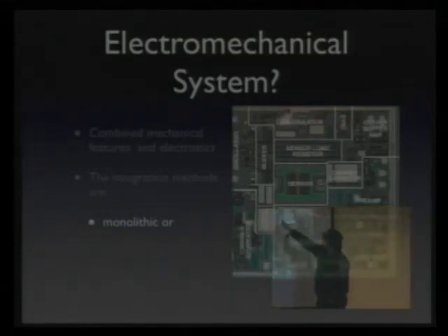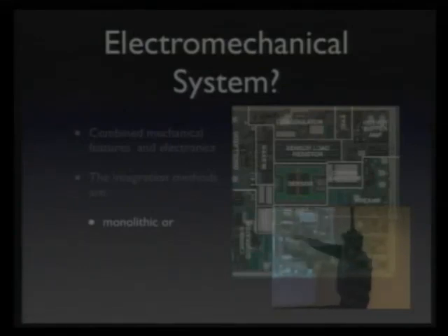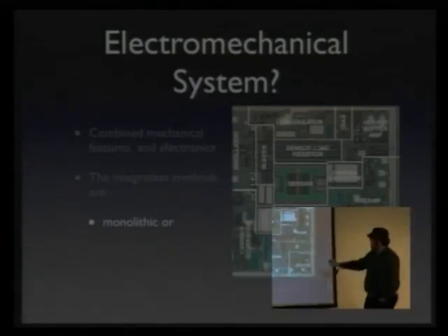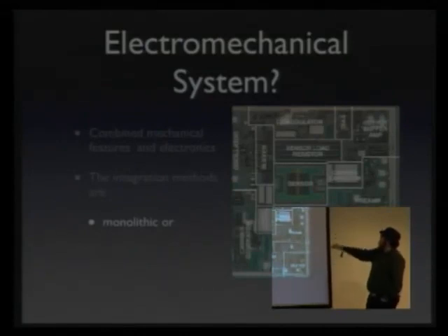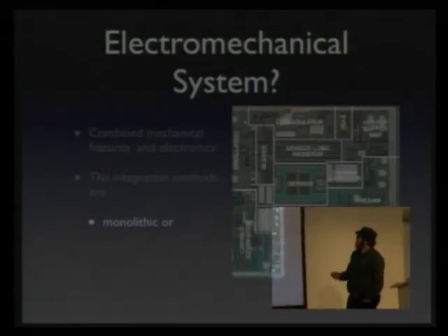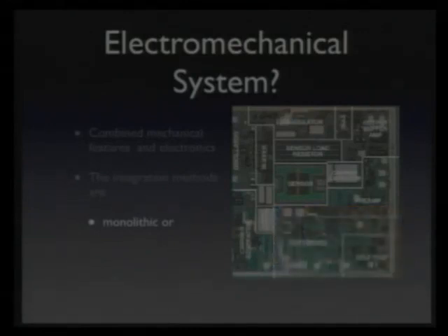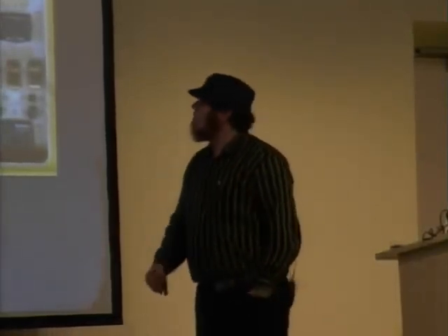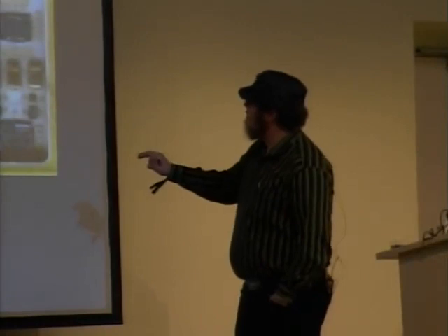This is the actual sensor, and all the rest of this is CMOS, all kinds of stuff. So you have self-test, pre-amplifying, then resistor load, buffers, whatever you want. You can already integrate in this way. Sometimes it depends on the process you're using to generate the actual mechanical part. You can't do this. So what you do then is hybrid integration.